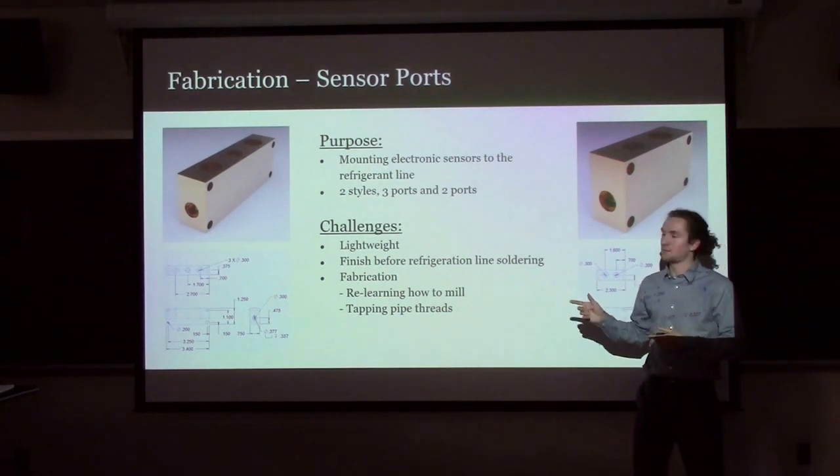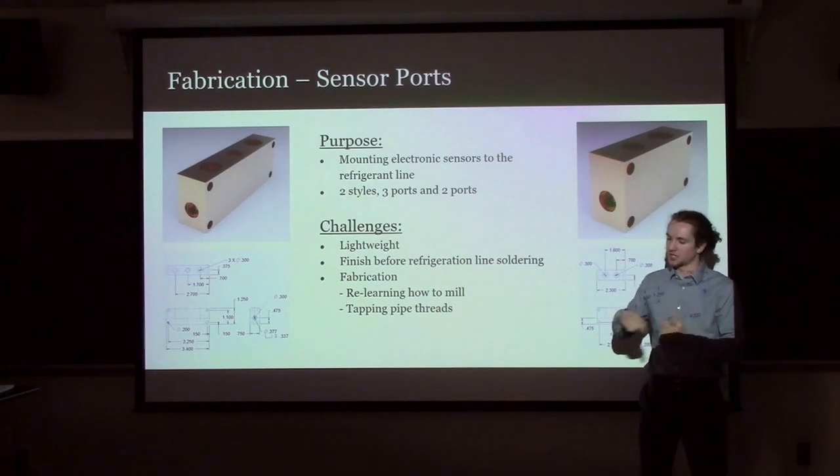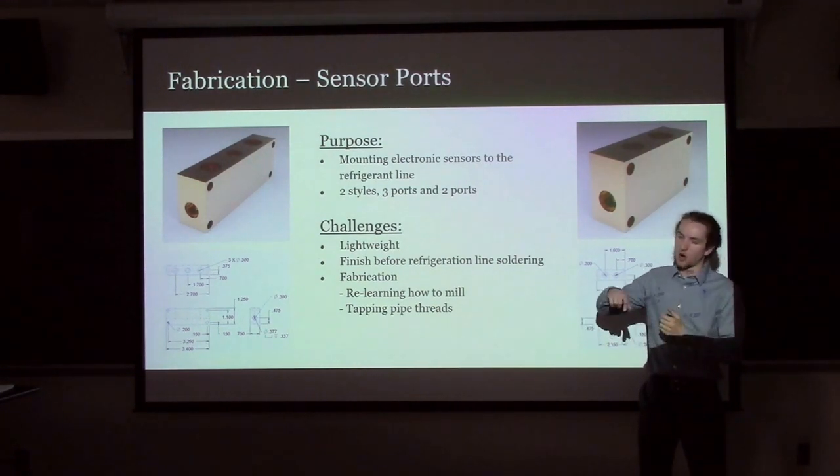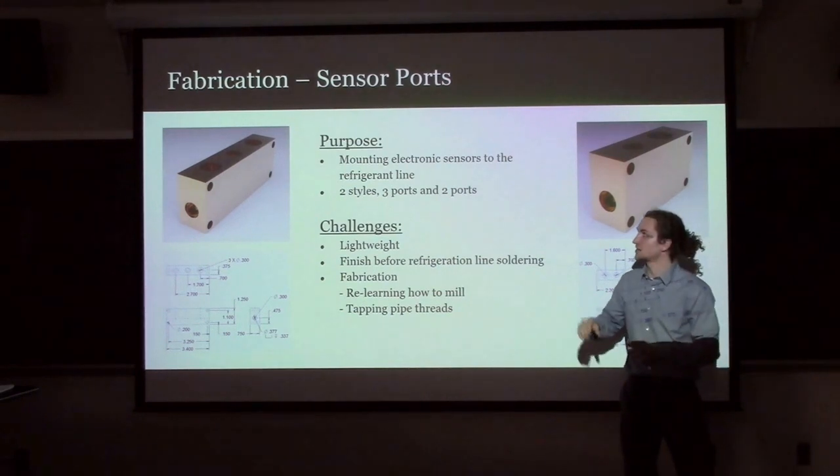And then also, tapping pipe threads is not easy. It's not like normal tapping because they're conical, so you have to work a lot harder to take out all that extra material. And if you actually go too deep, it will not seal. We had a little scare with that, but fortunately everything sealed correctly.